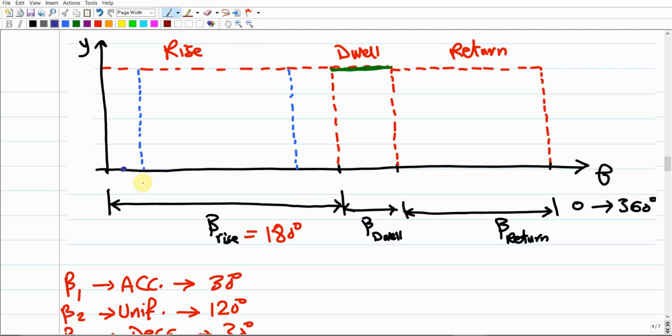So this is the beta 1 period, right? In half of the beta 1 period, mark a point. The same thing for the beta 3 period, in half of it, but near the end. This is the start point, remember, and this is the end point of the rise period, right? So from this midpoint, you're just going to measure in this direction beta 3 over 2, and in this direction, beta 1 over 2. Make sense? Then your objective is just to connect this point to this point.